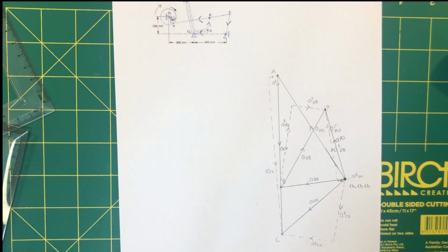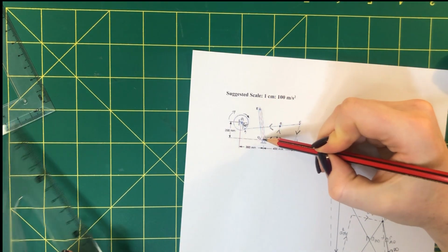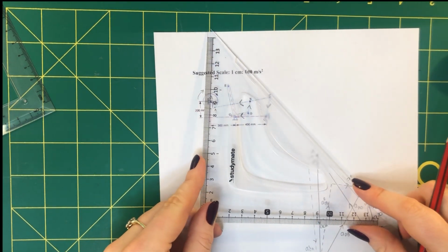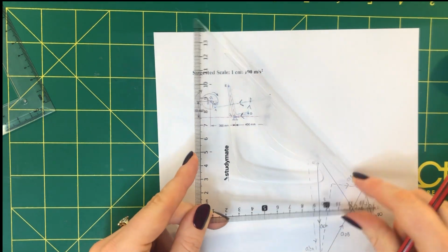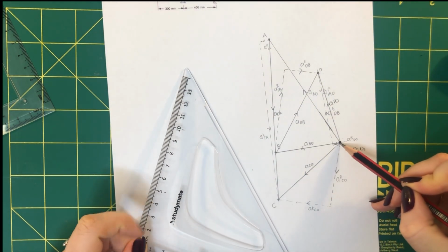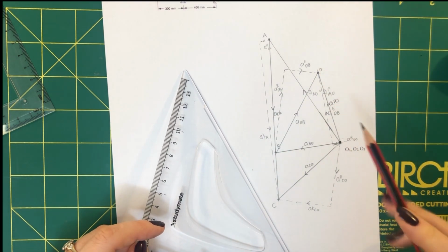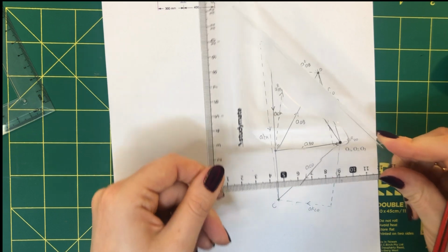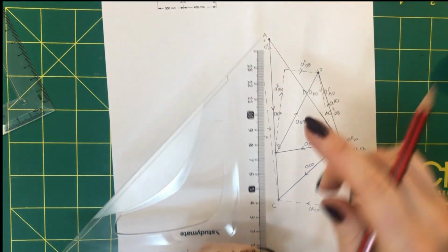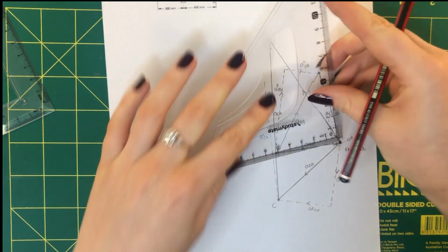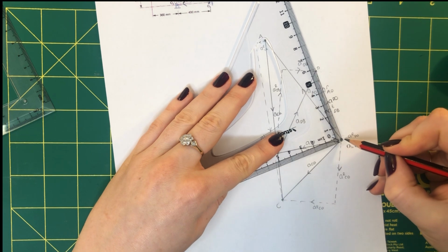So now we're ready to find the last point, point E. And you can see from the mechanism that E, O, and D are an L-shaped link. So if this is my L-shaped link, this is D, this is E, and they move together. From our diagram, we can see that point D is pointing upwards now. This is the total acceleration of D. So on my L link, if D points up, then E is going to be at 90 degrees to the other side. So let's draw in the direction.